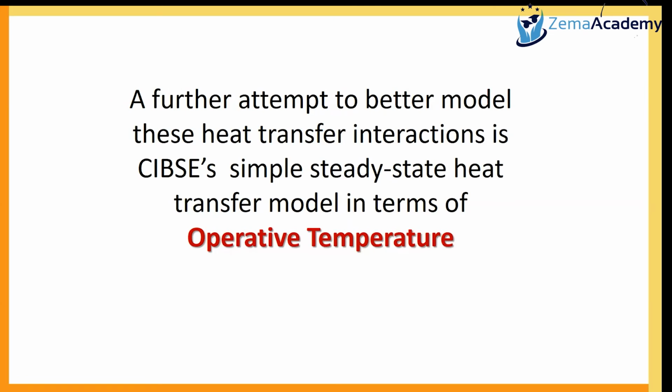We did a problem last time near the end in week 2, where we used a simplified equation for operative temperature, which was just the average between mean radiant temperature and the inside air temperature, if you remember. So from today and the next week's lecture, we will simplify the same model, but we will end up with a more complicated equation, consisting of the temperature difference between TC and TAO, which is the outside air temperature.